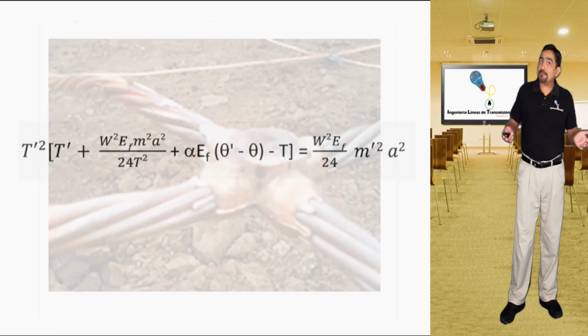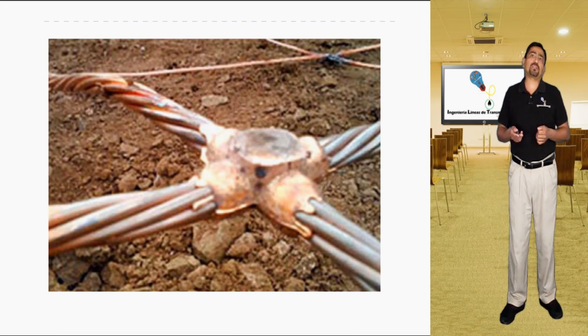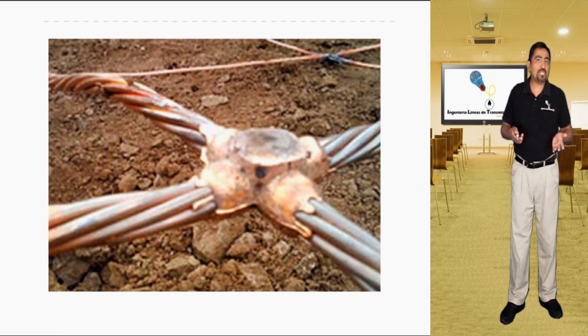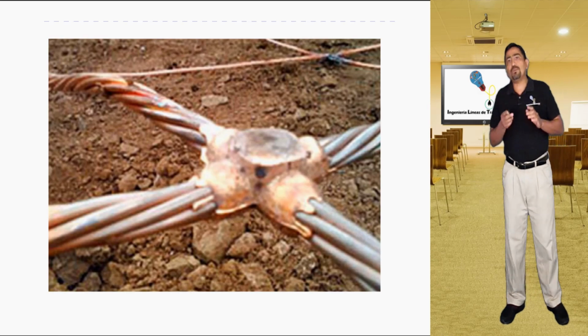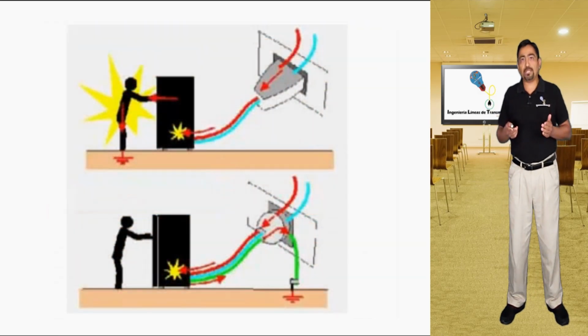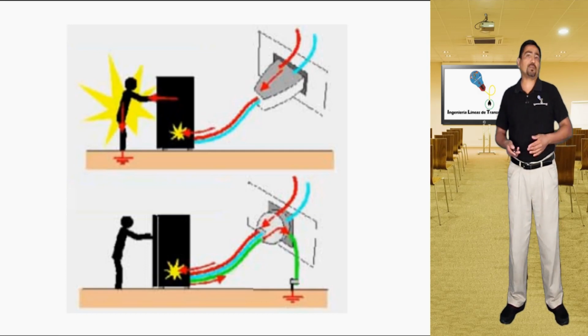Take a grounding system. In many cases, these systems are already standardized, but there are occasions where special configurations are required to solve conditions that have a very high resistivity. So, if we don't know the basic theory of the functioning of a grounding system, as what it really is, a low resistivity electrical circuit, we won't be able to make a deeper analysis when such situations arise.